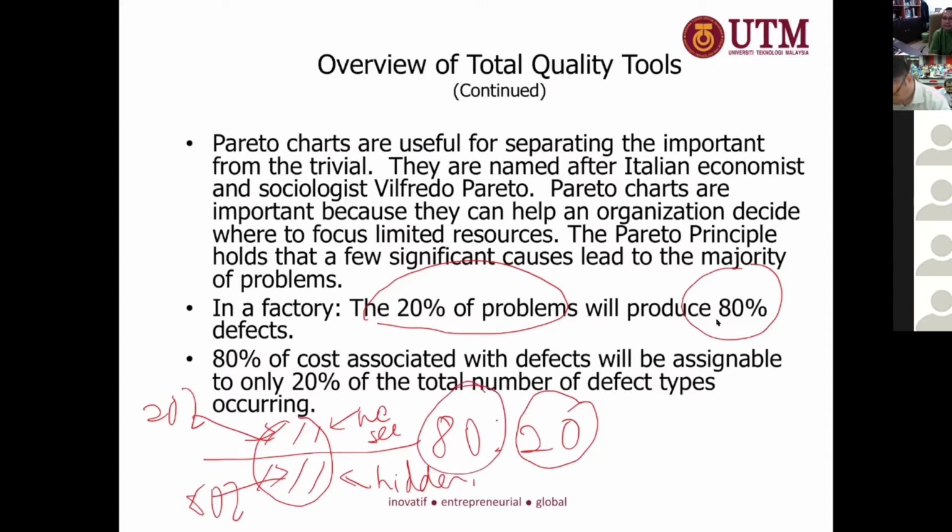So that's maybe one example. Or maybe we think of cars using a timing belt. We talk about cars using a timing belt, where at 60,000 kilometers or 80,000 kilometers we have to change the timing belt. No problem. Why do we extend up to 120,000 kilometers? That's small. The cost for changing the timing belt for a Proton Saga, for example, or Myvi, costs you around 200 ringgit. Why don't we extend it a bit, to a further 40,000 kilometers? We can save around 40 ringgit. Without you realizing it, your timing belt breaks.